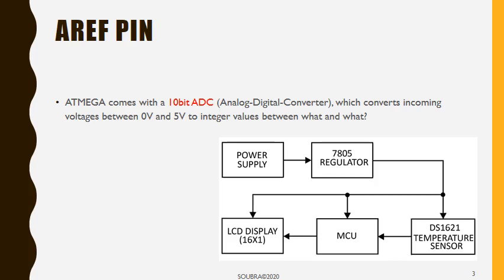All right. Now my question is, the temperature is a physical element, right? So it varies continuously. And usually, if you didn't know by now, the temperature is not really measured in Celsius or Fahrenheit or whatever. It's seen by the electronic component as what? As some kind of voltage. So the sensor sees the temperature as a voltage that is varying between 0 and 5 volts. Make sense?